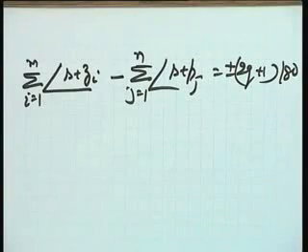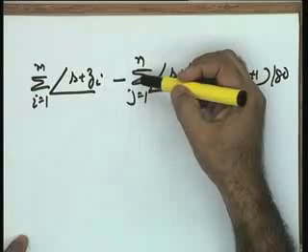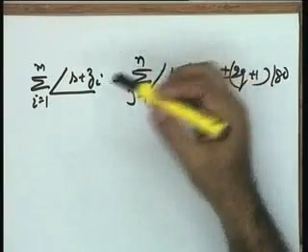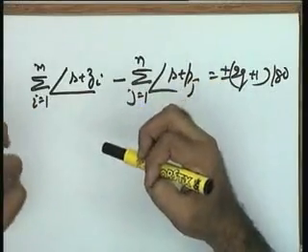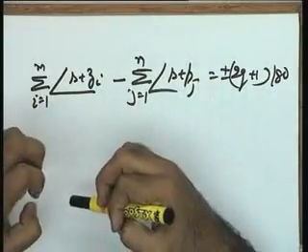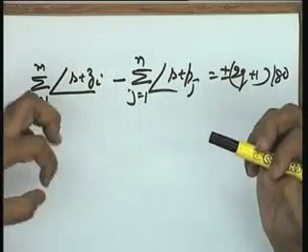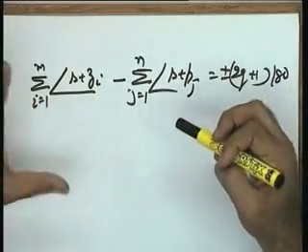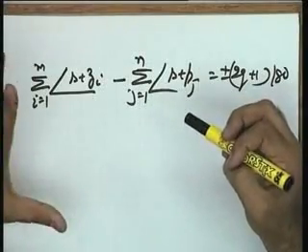This is your angle condition, please. Okay, you can see that. I think the summation should be clear because the angles are added, and this negative sign also should be clear. So, these are the two conditions. One is called the magnitude condition and the other is called the angle condition. So, any point which satisfies these two conditions is a point on the root locus plot.